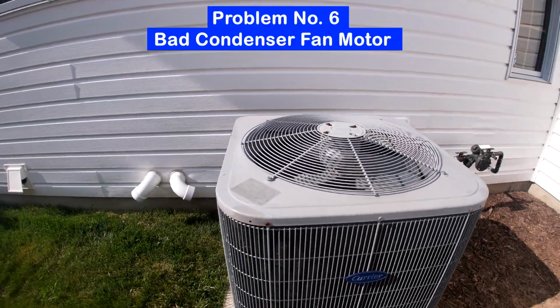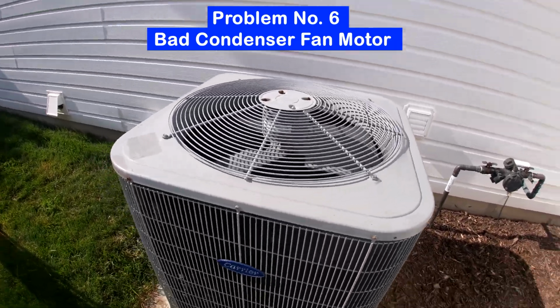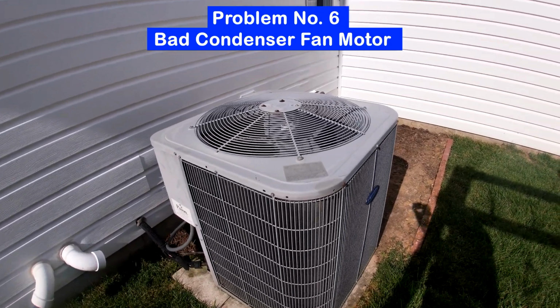If your outside air conditioner condenser compressor runs but your fan motor has a loud scraping sound, your fan motor bearing is most likely bad. In addition, if your fan motor does not turn at all or only turns for a minute or so, it is also most likely bad.